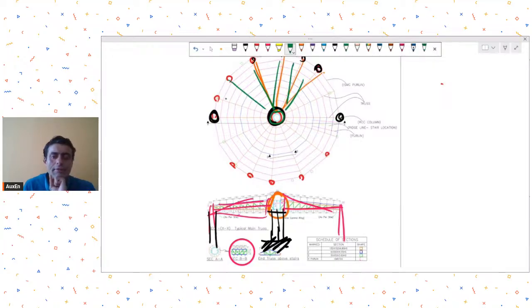So you cannot have truss only joining from one side and no truss from the other side, because that will lead to instability in your compression ring. So I think first you have to place this compression ring and prop it up, maybe create a platform or something so that it does not move here and there, and then you start installing your trusses.